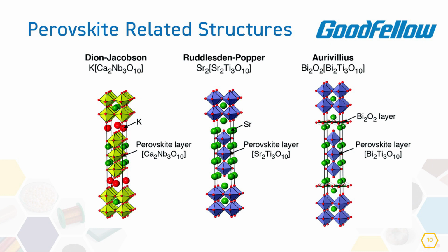Other methods to produce perovskites that can produce smaller particles have also been used. These include hydrothermal methods, where a solution of your desired cations is heated in what is known as a hydrothermal bomb. We also have a sol-gel method, where the cations are trapped close together in an organic gel before being heated, and this organic substance is burnt off. Because both of these are solution based rather than solid based, lower temperatures are required to make the reaction happen, and the particles produced are smaller.